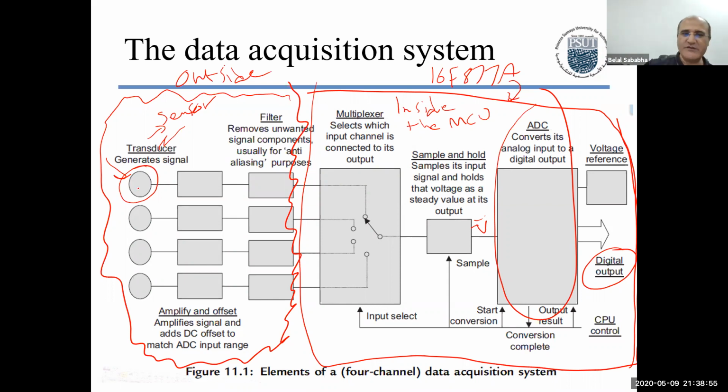But okay, you have a sensor. And I personally dealt with sensors that give you 1 millivolt. Well, this 1 millivolt, if we're talking about the 10-bit A to D I was talking about right now, is able to recognize 4.88 millivolts, right? So this is much lower than it can recognize.